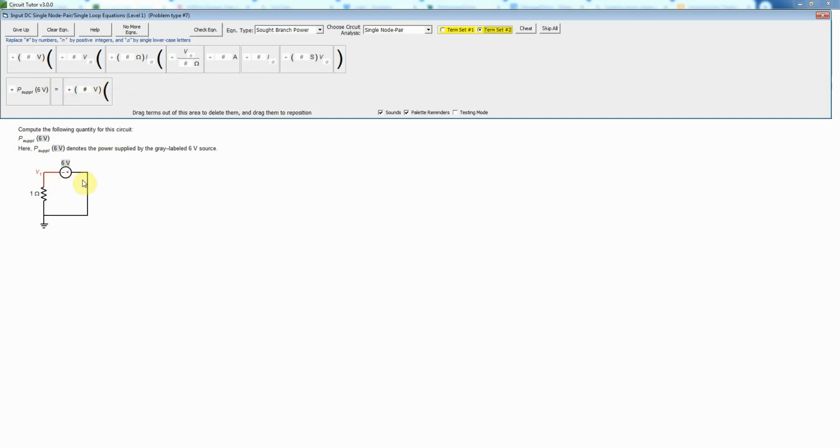So this is going to be the voltage, and remember it's V times I. So basically, it's going to be the voltage multiplied by the current from that, and I can find that, for example, using Ohm's law. It'd be one way of doing it in terms of the node voltage. Now, I always need to, of course, close my parentheses, so I put a right parenthesis in there. If you don't have closed parentheses, the equation will not be valid. It won't be accepted. So it's just like doing algebra. You have to have fully closed parentheses when you do this.